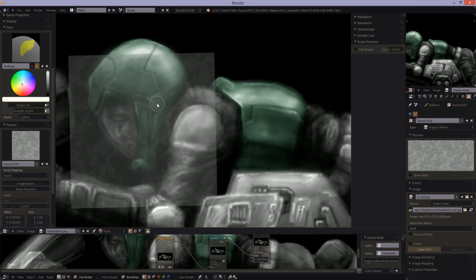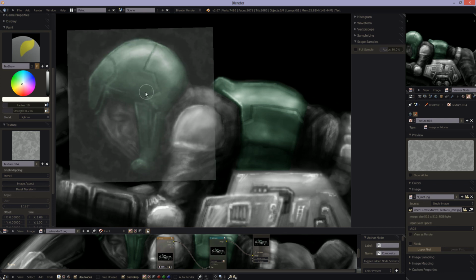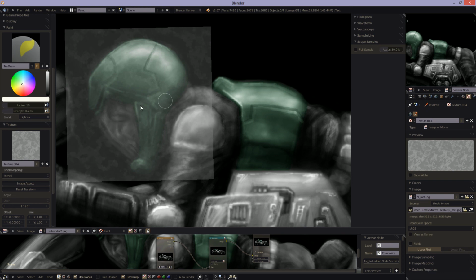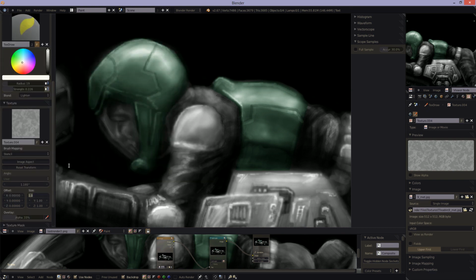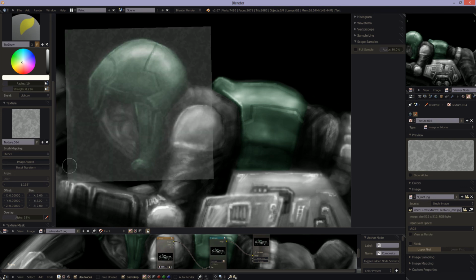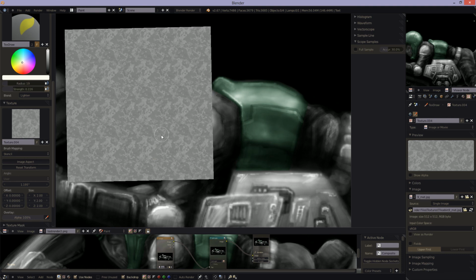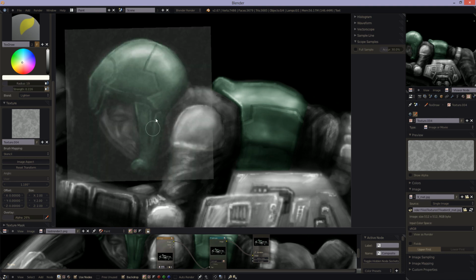If your image is, say, out here, then your texture will stop and you'll have a line. So you want to make sure that you've got enough coverage going on to do this. If you need a smaller version of this and it's tileable, you can change that here to maybe double the scale to make a smaller impression. To see it fully, this is what we're using, but we'll turn it down so we can see our painting underneath.